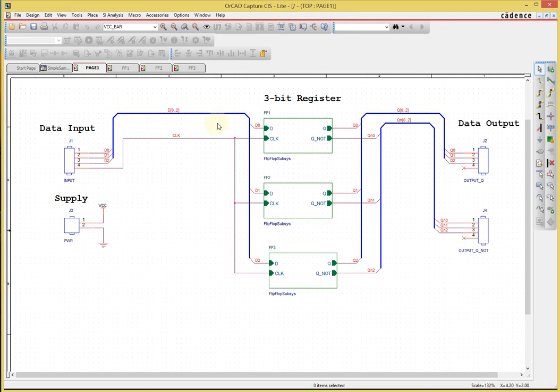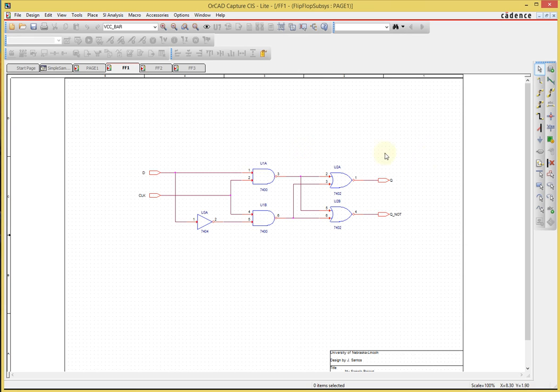So what we're aiming for, and we're going to start this from scratch, is a 3-bit hierarchical design. The reason why this is called a hierarchical design is because I am making use of what are called hierarchical blocks, which is a very nice feature for keeping your designs clean, and they make sense from a hierarchical design standpoint. If I take this block right here and I descend onto it by double clicking on it, I can see the structure and the implementation of that particular block.